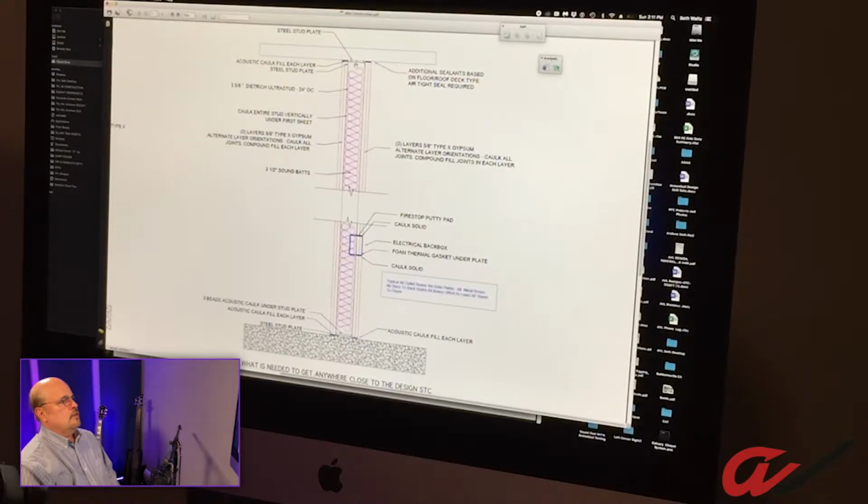So the question is, is Rockwool worth it? Which is a significantly more expensive type of insulation. In our opinion, if you're really trying to soundproof, it absolutely is. It stays in place better. It's denser because it's built out of rock instead of glass. The other thing with it is it does not settle over time, so it holds its dimension.